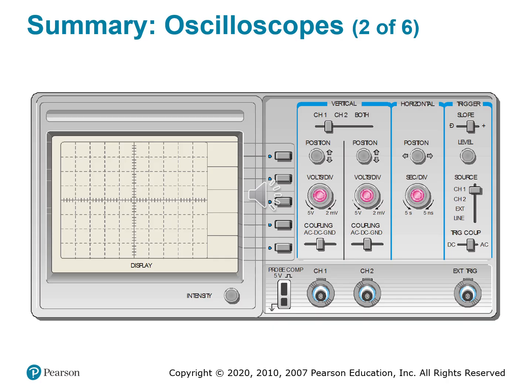And so you also have a selector to view channel 1 or channel 2, and 3 and 4 if your scope has more. Or, for example, channels 1 and 2 together. This is useful for comparing signals. In the horizontal section, in that middle section, the position control moves the waveform left or right, and the seconds per division knob sets the time base and how fast the trace moves across the screen. So a setting of 5 microseconds means each division represents 5 microseconds of time. And this is your time axis control. It lets you zoom in or out on the waveform timing.